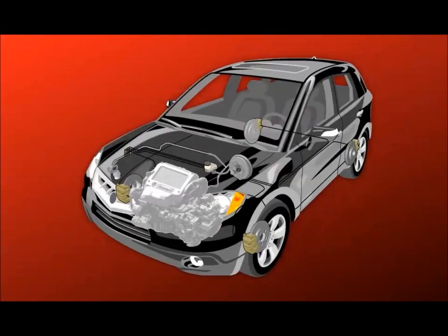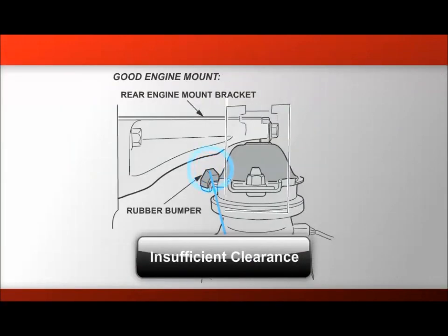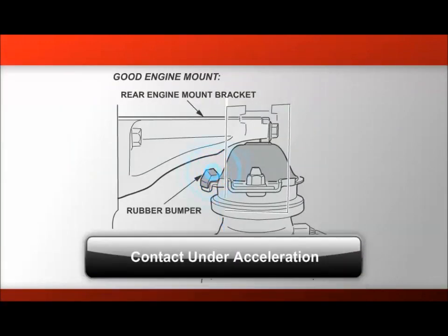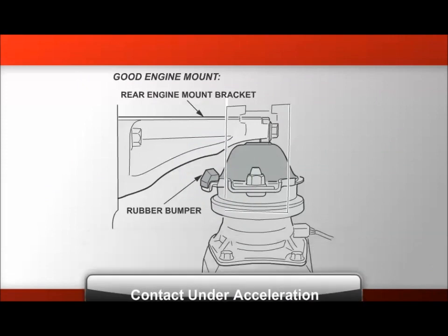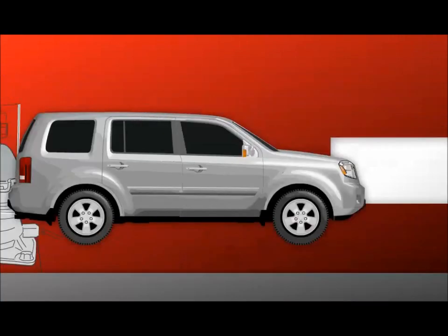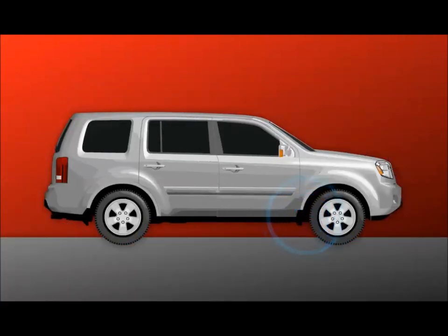During normal operation, torque moves the engine back and forth on the engine mounts. If a part has insufficient clearance, vibration transfer occurs when the engine rocks and two metal parts make contact. For instance, a vibration problem may only occur under acceleration or during braking.